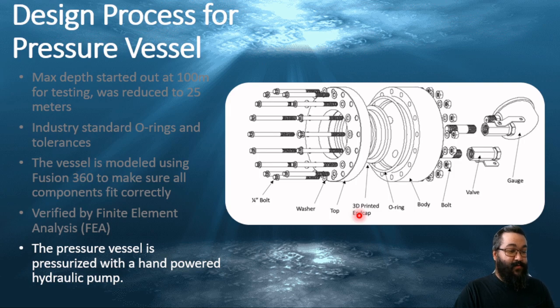So, going into how to pressurize the system. I chose water, because water is incompressible unlike air. Air, because it's compressible, will store a large amount of energy, and if there's a crack or a failure within the pressure vessel, that could lead to a catastrophic failure as an explosion with air. Where with water, it'll just leak out of the failure spot.